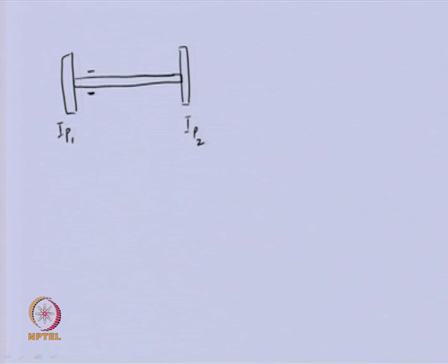This is mounted on frictionless bearings and is free to oscillate on them. As such, the bearings are not resisting the motion of this rotor system. Earlier we solved this using Newton's law. Now, we will use the transfer matrix method to obtain the natural frequency for such a system.